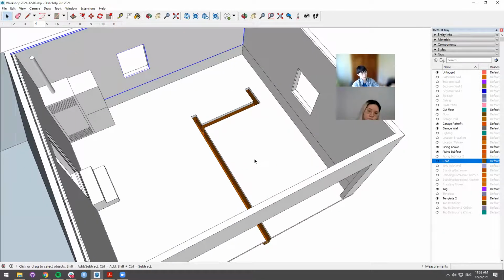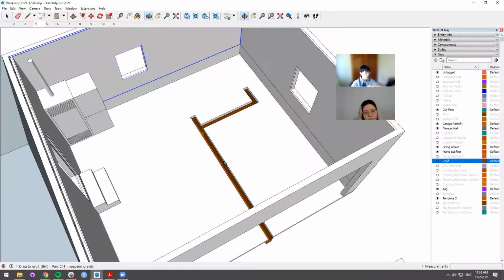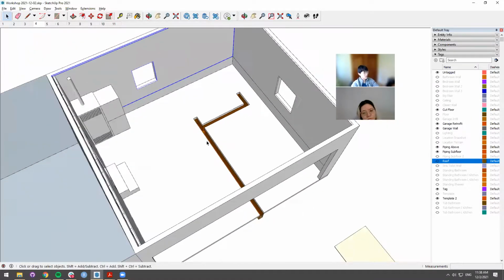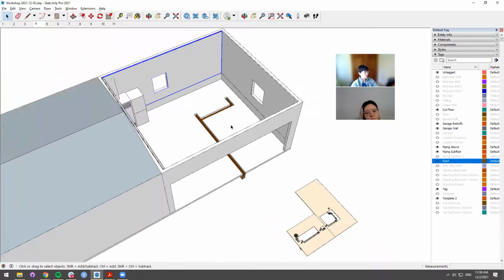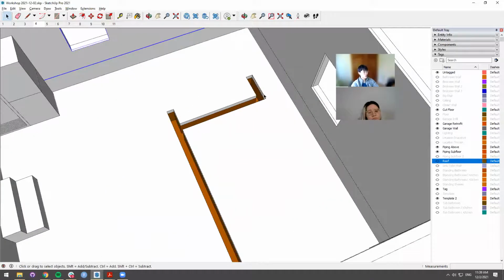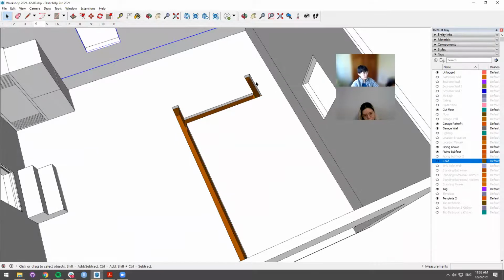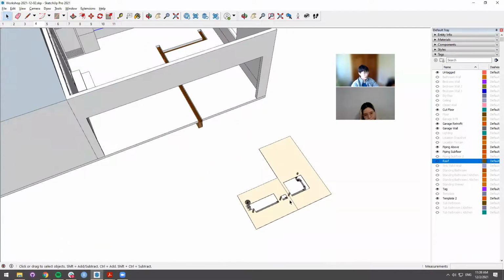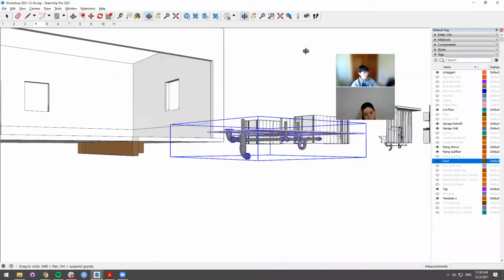You circumvent this entirely if you can do a raised floor design, but at some point the sewer system needs to get back into the ground. That might happen one time or outside in a raised floor setting. But in this version, you can see that the contractor would have identified where to cut out based on that template. But going way beyond that, they would actually pre-assemble the plumbing system.